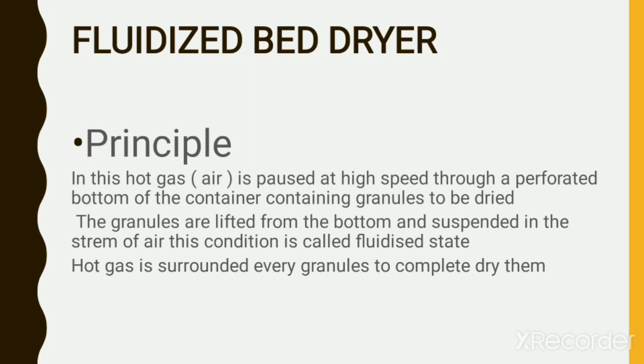In this, hot gas or air is passed at high speed through a perforated bottom of the container containing granules to be dried. The granules are lifted from the bottom and suspended in the stream of air. This condition is called a fluidized state. Hot gas surrounds every granule to completely dry them.